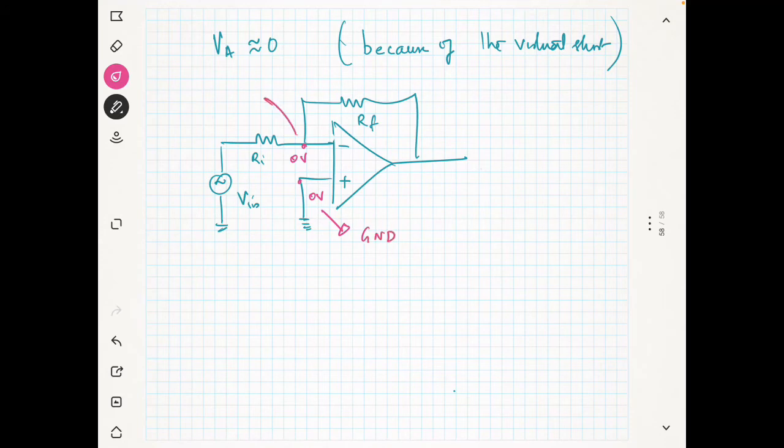So this voltage is also at ground, but actually it is not connected to the ground. It is not in a true sense, but in another sense. It will follow the same voltage of the non-inverting terminal, or we can say that they are virtually short, or they are virtual grounds. So this is the concept of virtual ground in op amp. This is a very important concept in analyzing electronic circuits.